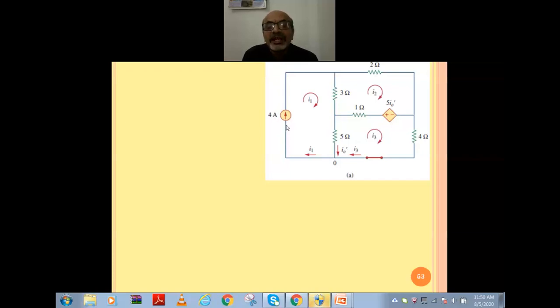as acting alone each time, and let us say that each of these supplies the current as I0 dash and I0 double dash. So here let us say that I0 dash is the current which is supplied by the 4 ampere alone, and I0 double dash is the current which is supplied by the 20 volt source alone. Now remember, as this is a dependent source, we will not remove this for the calculation when each source is acting alone, and therefore in the first step we will start with I0 dash.